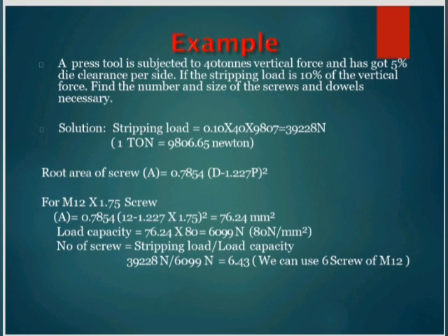Stripping load is 39228 Newton divided by 6099 Newton, which is 6.43. So, we can use 6 screws for M12 size.